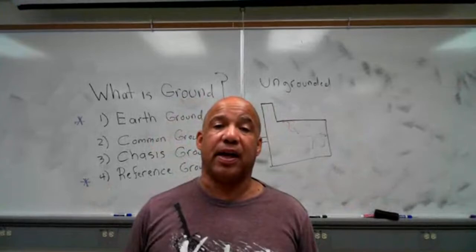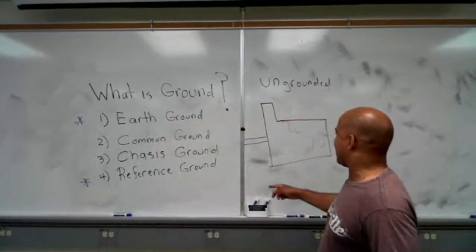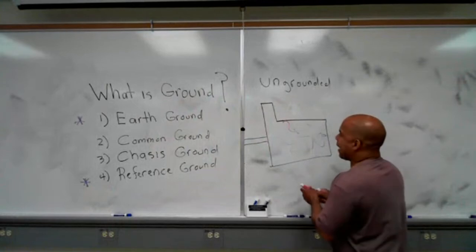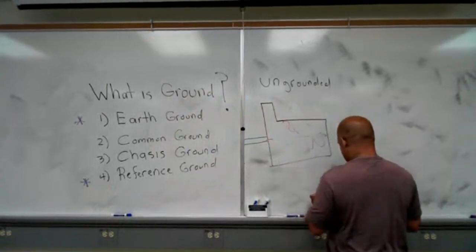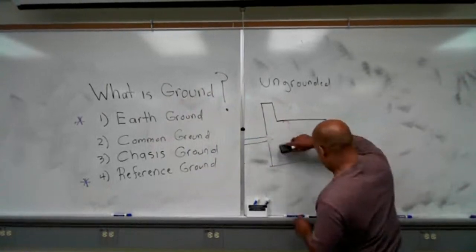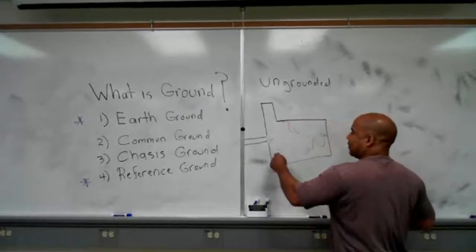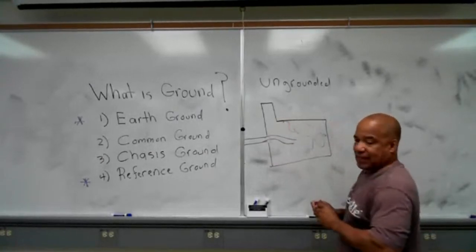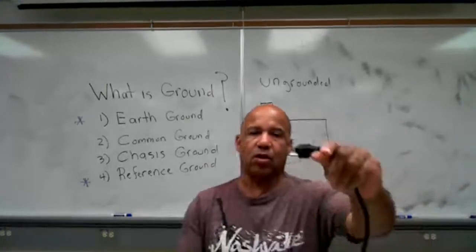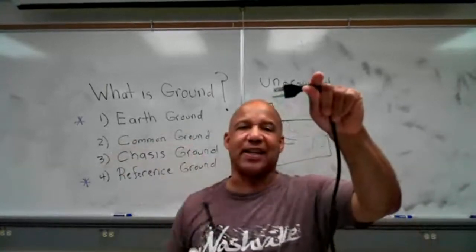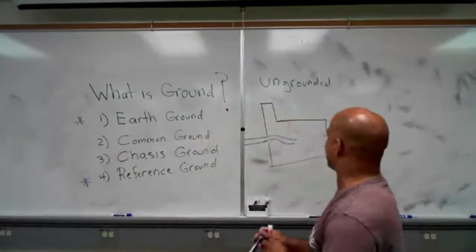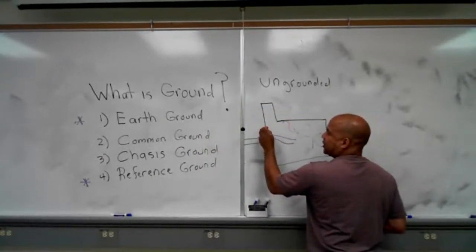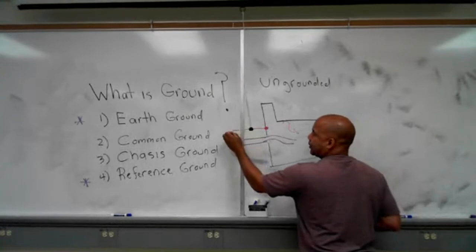Everywhere there's electricity now. But what you do is you add to these two power wires a third wire. Now these power wires actually go into the machine to the electronics inside of the machine. So maybe you're powering the motor or whatever else is in there. But that third prong on here doesn't connect to anything electrical. It actually connects to the case or the chassis of the machine itself, and it goes out to ground.